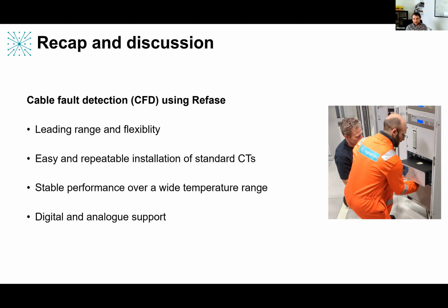Yeah, there's quite a good CIGRE report on this topic, a CIGRE B5 report, which looks at all the different technologies that can help here, and it highlights this. It talks about this exact issue of using impedance to help you find the exact fault location, and it's quite hard. Part of the issue is also that you need voltage measurements involved, which is potentially inconvenient or expensive as well.